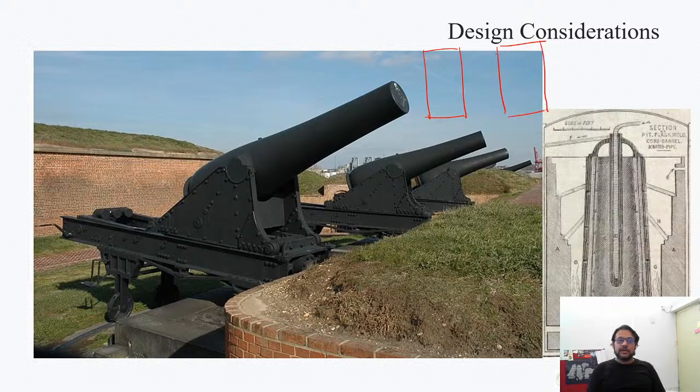What he wanted to do was make this portion much harder. The way you make this material much harder is to have smaller grain structures at this location, and there should be a significant amount of it here. Here there may be some layers which are harder, but he wanted essentially something like this. What he did was quite ingenious. He made this kind of rod as the core, and inside the core you would flow water. Water would flow in and it would come out.